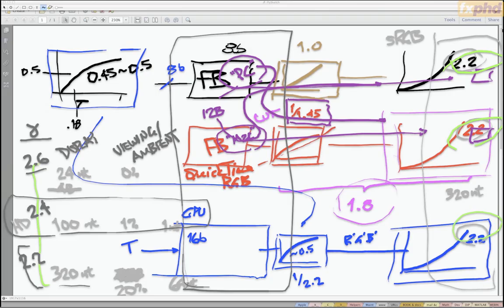So as you increase the so-called brightness setting, you are basically decreasing gamma down towards 2.2 or even towards 2.0. So that physical function is built into a CRT, but a DLP, PDP, OLED, LCD, they're all different. Those new displays do have compatibility circuitry to make them behave as if they're the old displays. But it's really valuable for us to maintain that old display mapping from code level to light level, because it's hugely important for compatibility reasons.